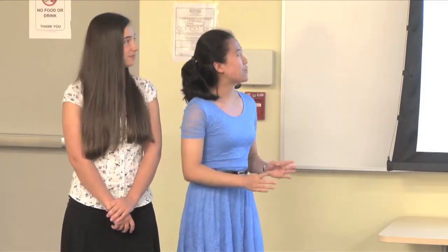In this experiment, we focused on one variable, which was the percentage of API. The other three factors that Liz mentioned, the RPM, the fill, and the blending time, were kept constant after our preliminary research. However, this could lead to a confounding of factors. A confounding factor is a third variable which can influence the relationship being studied between two other variables. In our case, that would be the percentage of API and the flow function. Ideally, we would have individually tested the RPM, the fill, and the blending time to see which combination produced the most homogeneous blend in the end. But because of the time restraints of this project, it was not feasible for us to do so.